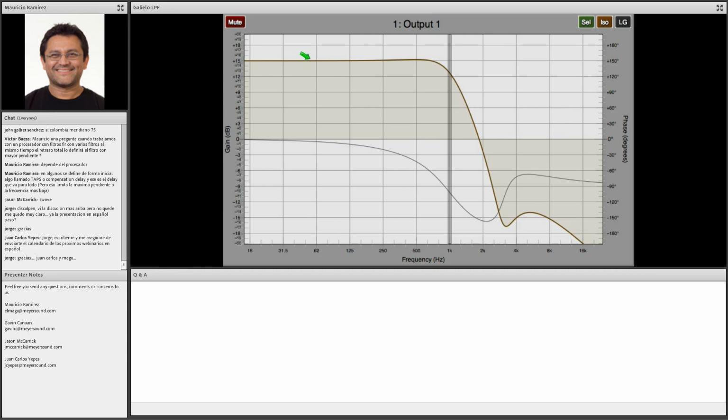And if I have 0 exactly here and I have 3 decibels per division, then from the current 0, this is 1, 2, 3, 4, 5, 6, 7, 8, 9, 10, 30. It's around 28 decibels of ripple. So right now you can see a commercial processor that is using a filter as the one that I have described.